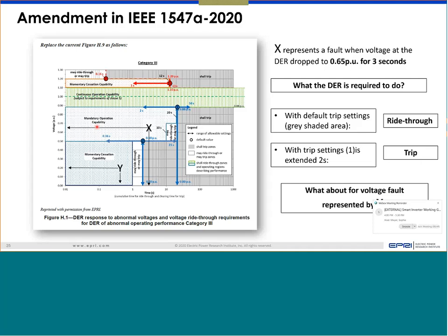On the other hand, in one of the recent projects, over the last 6 to 9 months, again the same example that we mentioned, the nighttime reactive power support, we are frequently hearing from the system operator, again, we don't have any direct contact with the inverter vendor, okay, this failed, this happened, we need to troubleshoot. So it might be one bad product or one bad installation or something that may trigger that fault. But in general, if it's a quality product that has gone through the standard testing and regression process, like some of the major manufacturers, then you can rely on that inverter.